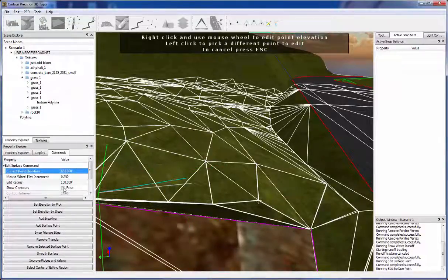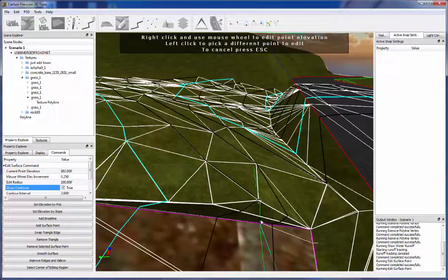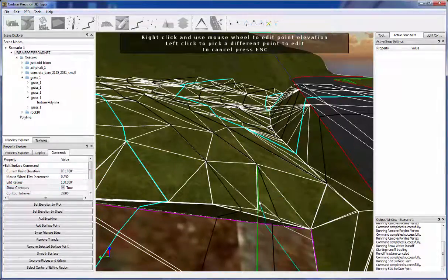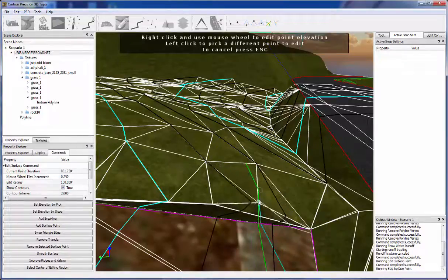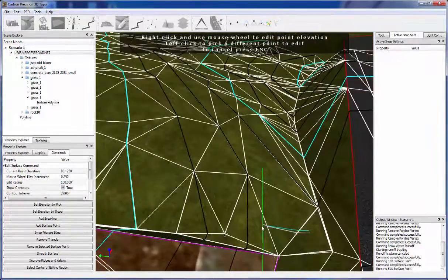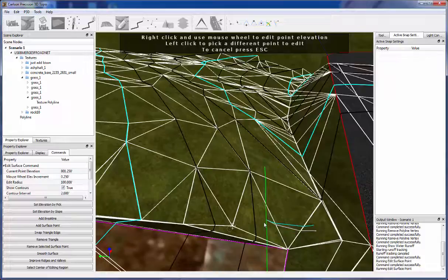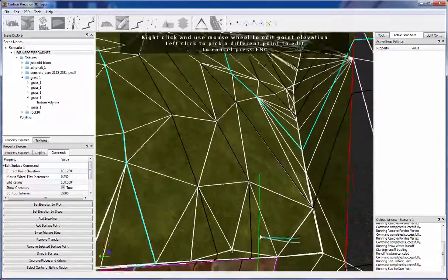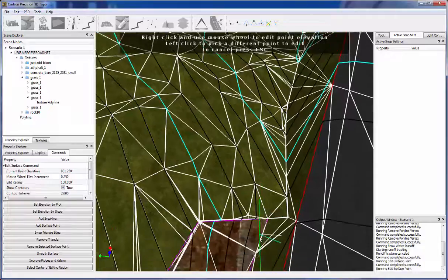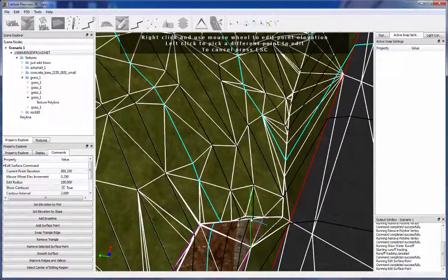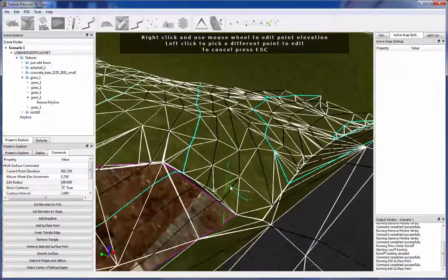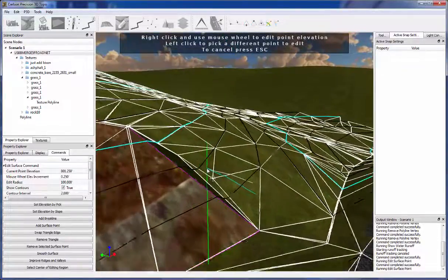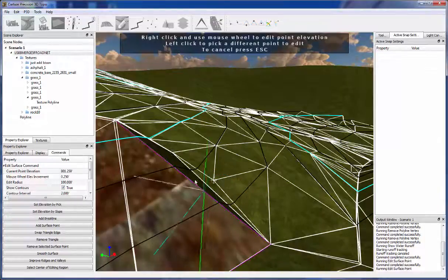I can show contours so that as you make modifications to the surface, you'll notice that the contours change and are modified dynamically to give you that instant feedback as to what your design surface looks like. So you basically get the best of both worlds. You get to see all your triangles and faces in this CAD perspective of the 2D plan, but then also we allow you to rotate that into 3D so that you can get more detail as far as what it looks like, and you're in a multi-textured environment, which gives you additional visual cues on things to do.